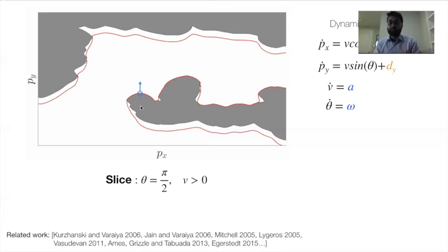If I were to show the backward reachable set slice for a heading of -π/2, meaning the robot is facing downwards towards the bottom of the screen, you will see a retraction in the boundary here and the boundary hugging the obstacle over here. These shapes are somewhat intuitive for this simple 4-dimensional system, but they get very complex as we move to, for example, quadrotors. But the reachability math itself is general and can be applied to general autonomous systems.